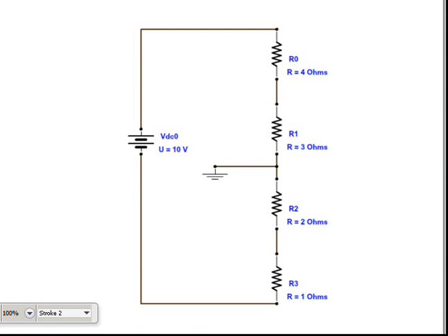Okay, here we have a 4 resistor string. And of course it is a series string, only one path for current. But in that series string now, we have a reference point. Remember, this reference point is nothing more than a reference for making measurements. It says, this is where my ground probe goes. A meter has 2 probes, a positive and negative. This is where the negative probe goes.